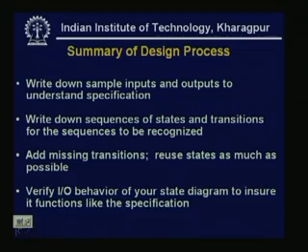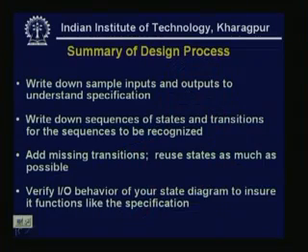There can be problems where more than one input bit pattern gives output 1, say 0 1 0 as well as 1 1 1, where the machine should give a 1 output. So we do the state transitions. Then add missing transitions, reuse states as much as possible, and verify the I/O behavior of your state diagram to ensure it functions according to the specifications.